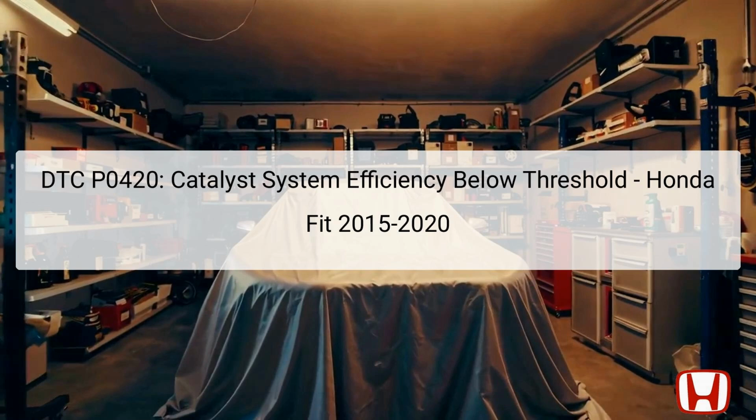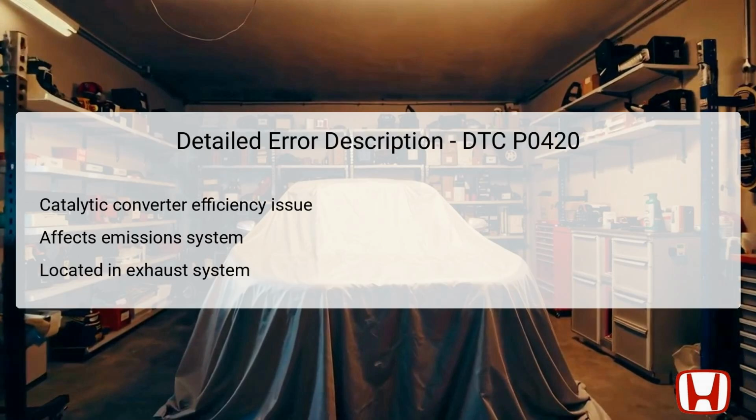The issue may stem from the design or condition of the fuel system or exhaust system components. If unaddressed, the vehicle can experience performance issues, increased emissions, and potential long-term damage to the engine. Understanding the causes, symptoms, and troubleshooting methods for this DTC is essential for maintaining vehicle performance and compliance with environmental standards. DTC P0420 indicates that the efficiency of the catalytic converter is below the preset threshold.